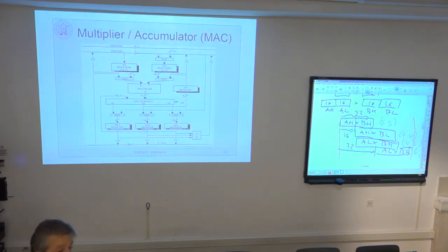And only then, when I have the final result, I can try to find where the leading bit is, 0, 1, depending on the sign, and then shift to the right whatever number of bit positions I need to have the value in a single word, 16-bit, or maybe double word at 32-bit. Okay? So that is the purpose of this 8-bit extension.